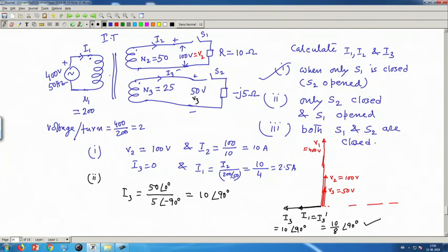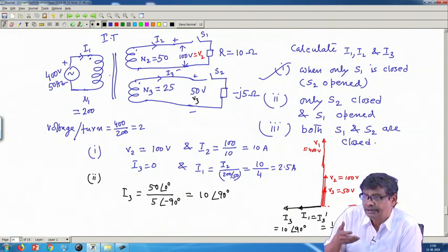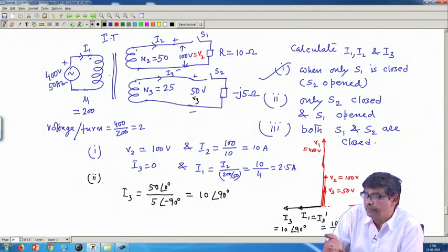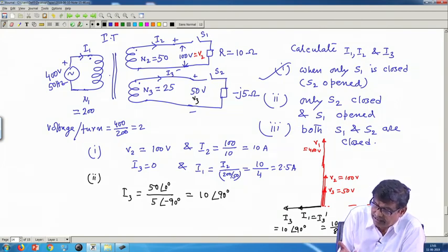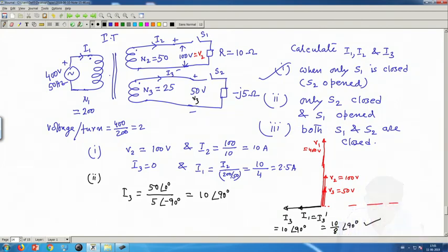Please try to follow me. So far, in the previous examples, I was just telling impedance values to tell you about the rated current, but now I am in a position to go to a slightly advanced stage, that impedance may be complex and how to calculate the currents. Had it been an RL circuit, the phase angle of the impedance I could also take into account, but wherever there is your secondary current, the reflected current because of that must be there. So, this is the thing.